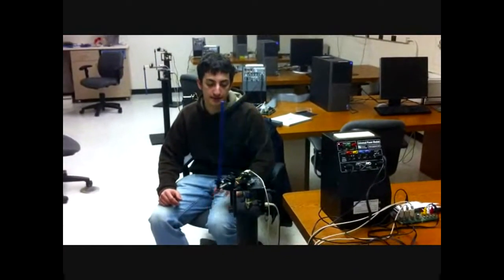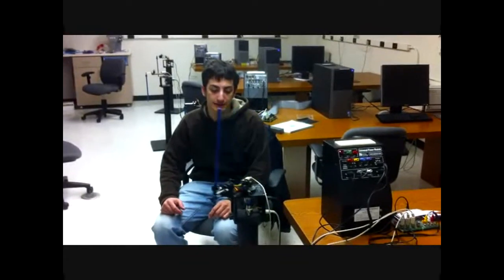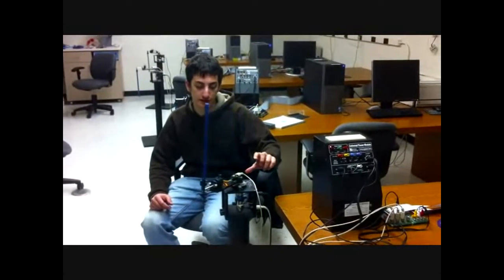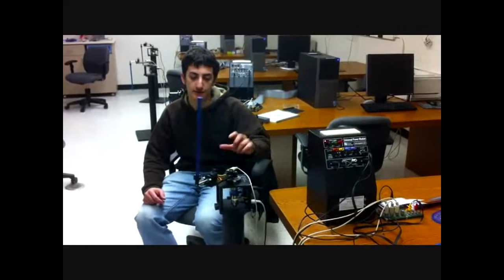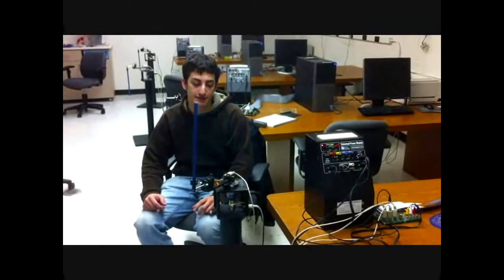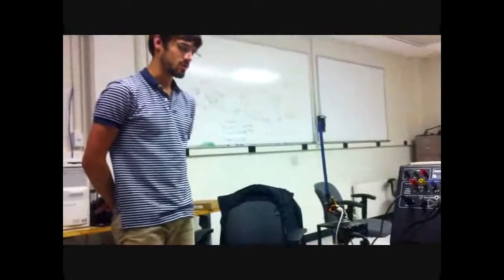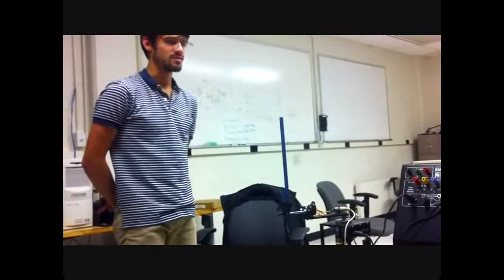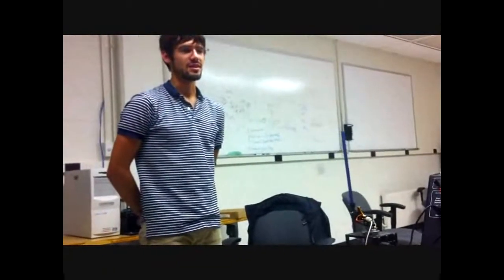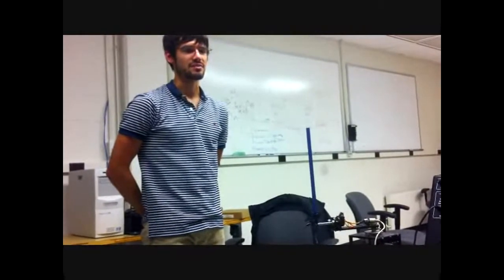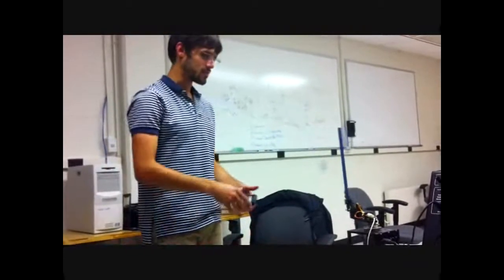So we use these two sensors in Simulink to take the derivatives of each of the Q1, the angle of the rotor, and Q2, the angle of the pendulum, to derive our four state variables. Okay, so the robot swings up, and now it's oscillating at 1.5 radians per second between pi over 8 and pi over 4 and negative pi over 4.